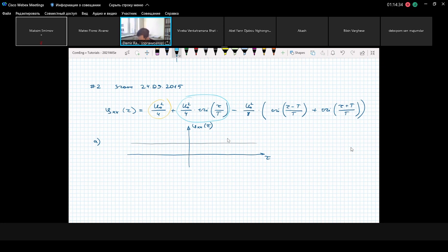The second part: at the origin we have a triangular function which goes from minus T to capital T. These are the points where we have delay minus T and capital T. The original amplitude of the DC component was u0 squared over 4, and I can place this triangular above the DC component, because of course they come together.